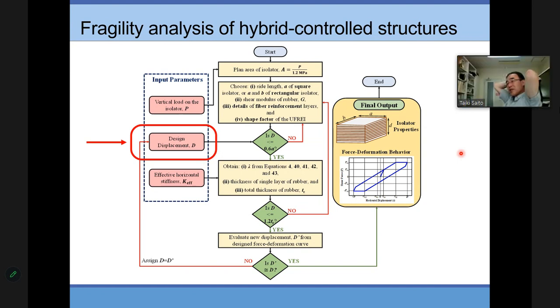But if it's a linear system, we know how TMD works, right? For the frequency response, we can apply this formula for combining equivalent damping and equivalent stiffness of the isolator layer. And then we can find some optimum design from them. And also you can compare with time history analysis to check the accuracy.